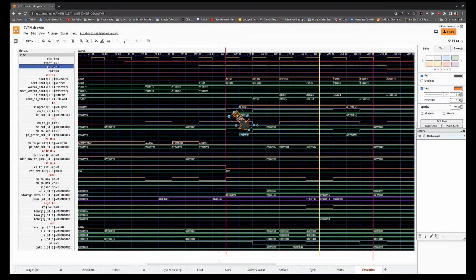Let's look at the register file during the RType instruction. We can see here that as it's moving along through the instruction, we're doing our arithmetic, and eventually we're going to reach the write back stage, and that's where we bring the write signal down low, and we take whatever was in the output of our register down here, which is B, so it's set up for the load, and we write it into x3. And that's exactly what's happening.